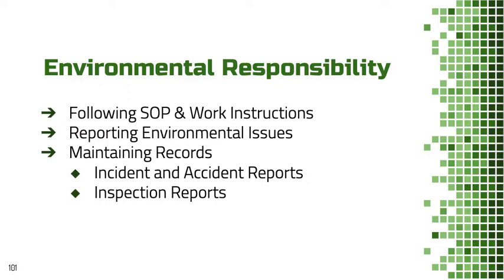Now, using resources efficiently includes reducing the materials that we actually use and also considering whether the energy and water use is efficient by doing things like testing the pipes to make sure that there are no leaks, to make sure we have fixtures and fittings that are efficient. If I'm thinking about installation of a shower, for example, making sure it has a WELS star rating. I know my shower delivers 9 litres per minute, which is the current recommendation. Having efficient fittings, insulation in the house to manage heat control and cooling.